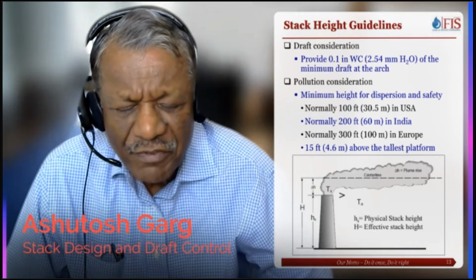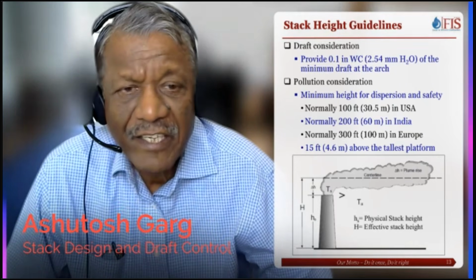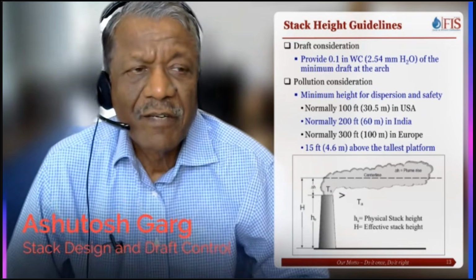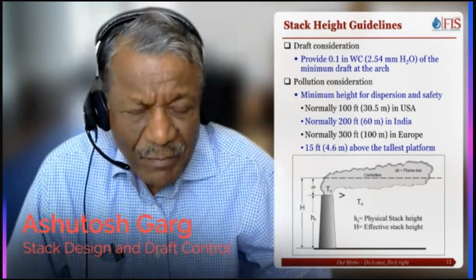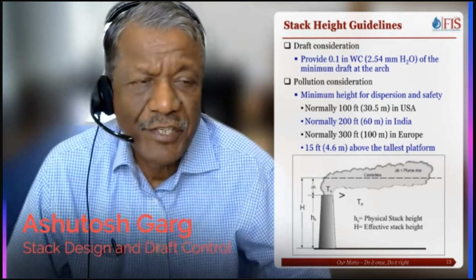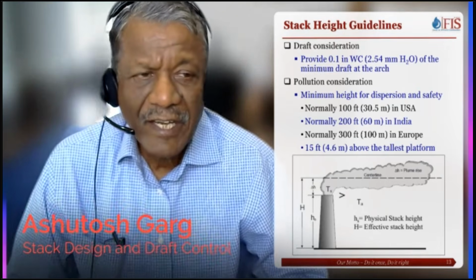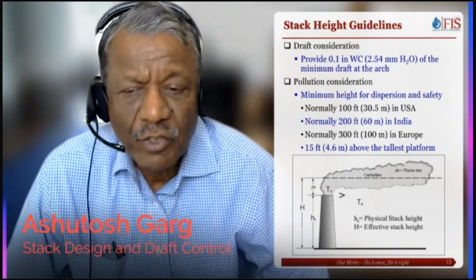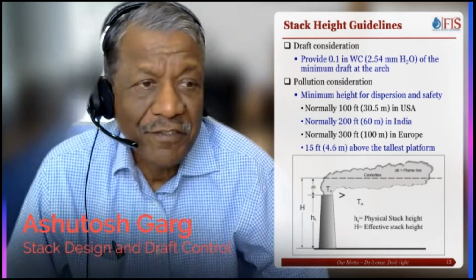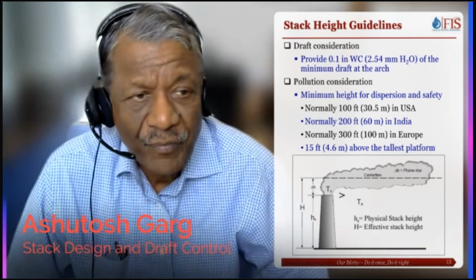In US, most of the heaters are burning clean natural gas. And because of that reason, 30 meters was deemed sufficient. In India, typical stack height requirements have been 60 meters or 200 feet.